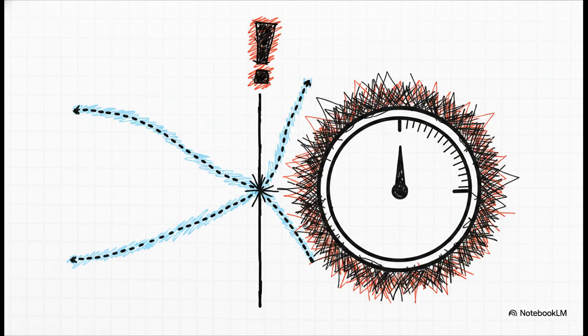And right here is the danger zone. As the gain gets higher, those vertical paths are heading straight for the imaginary axis, which is the absolute edge of the cliff for system stability. If we do the math, they cross the line exactly at positive and negative j 1.414. And guess what the gain dial reads at that exact moment? 6. When K equals 6, we are literally 1 millimeter away from complete system failure.